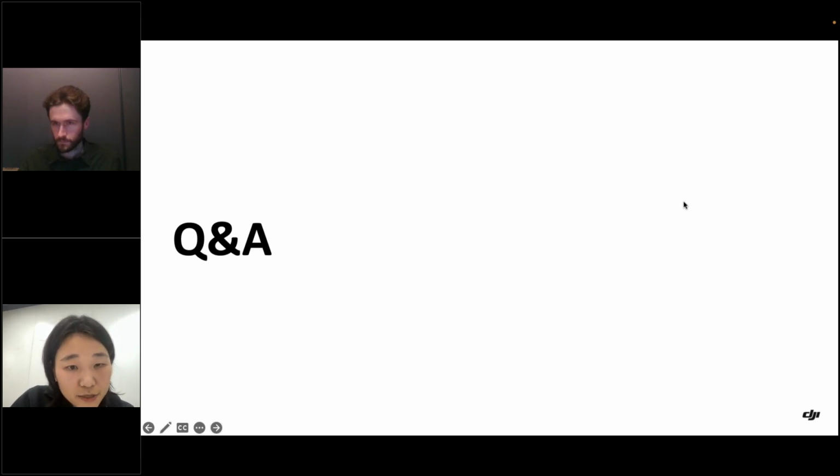And okay. The next question, will there be a way to update the base station coordinates for imagery, not LiDAR? Okay, so as I understand, you're possibly asking also about the PPK workflow for the photogrammetry processing, because as I understand, there is a way to do the PPK processing directly for LiDAR right now in Terra, and you can also adjust the base station center coordinate.